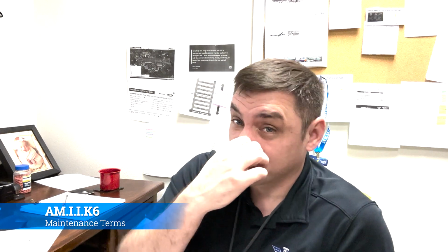Okay, so Group 1 examples would be something like hydraulics, the fuel supply system, things that simply make the engine run. If all of a sudden you lost all of your electrical power and you have a FADEC controlled system, that means generators, batteries, everything's gone. Well, you basically got a glider on your hands. You're going to deploy the RAT, and you're going to try to get the power coming back on. But you're in an in-flight diversion scenario. You need to get on the ground quick. That's a Group 1 system.